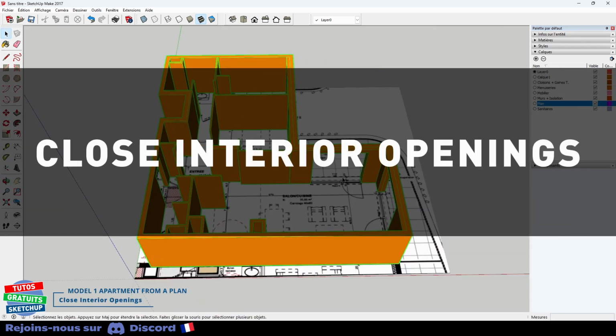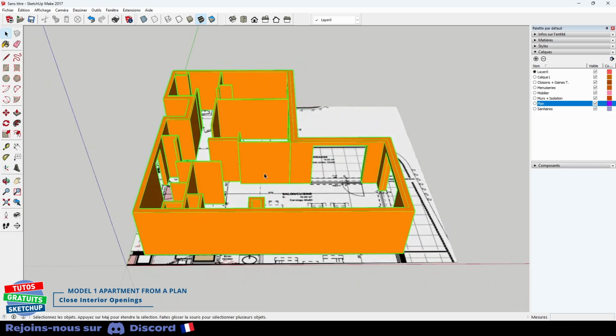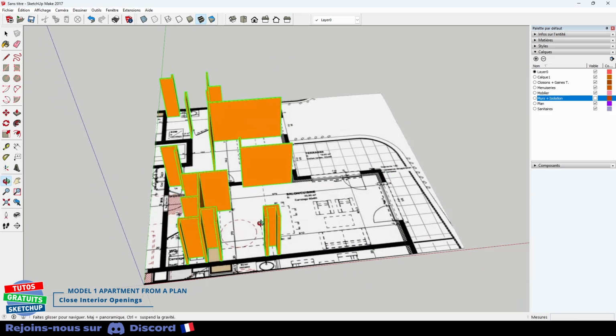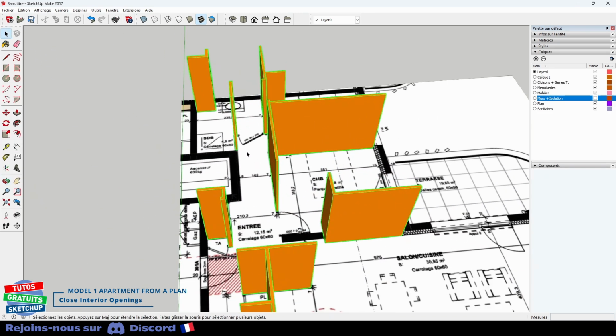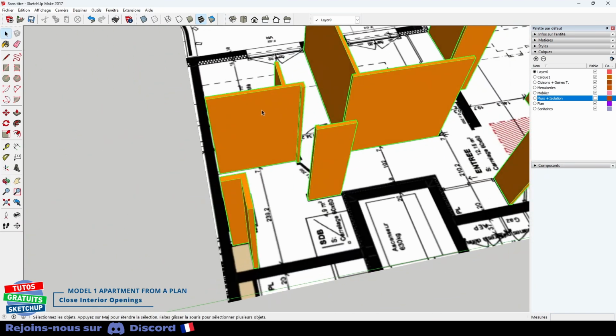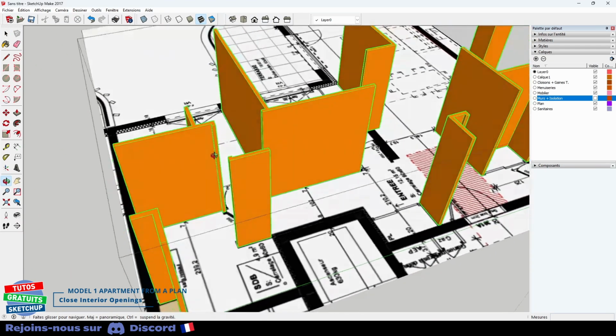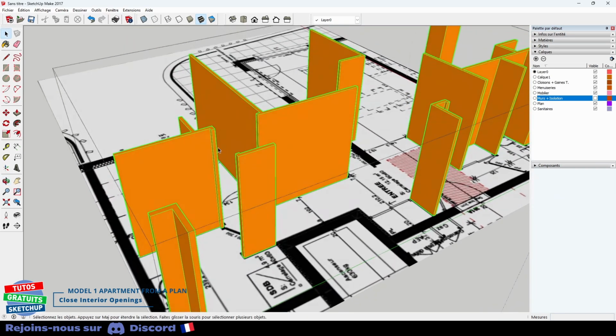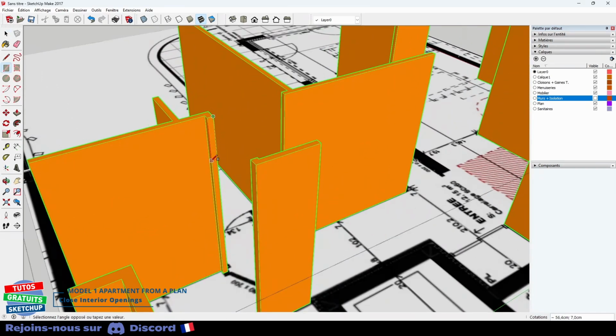Now I need to seal the openings above the interior doors. I mask the walls. I keep the map to identify where there are doors. Just one here already. Double-click to open my group, which contains my partitions. I draw a rectangle as usual on the height. This time, however, I type 40. I confirm. Interior doors are always smaller.